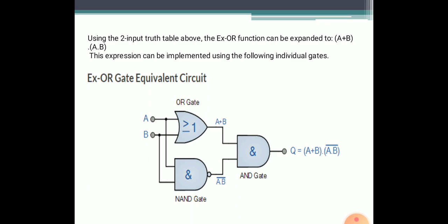One of the applications of the XOR gate is that it can be used as a 1-bit adder that adds any 2 bits together to produce 1 bit as output. For instance, if we add 1 plus 1 in binary, we can expect a 2-bit answer, that is 10, which means 2 in decimal. The trailing sum bit in this output is achieved with the XOR gate, and the preceding carry bit is calculated using an AND gate. This is the primary principle in half adders. A slightly larger full adder circuit can be chained together to add longer binary numbers.